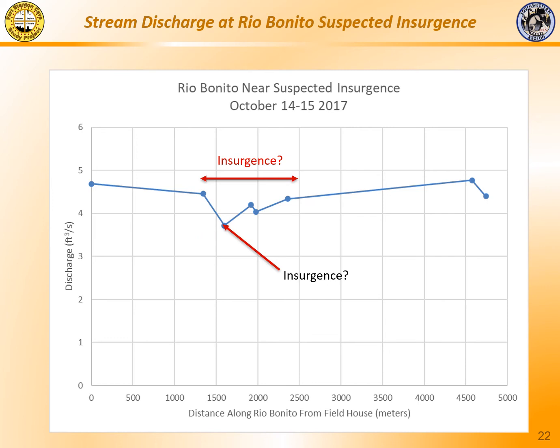So what's happening here? Well, each of these measurements has some error associated with it. If we make a really good stream flow measurement, we say it has a 5 to 10% error. If we're not in a nice straight channel with uniform flow, the measurement error can be much higher. And that may be what happened here: this measurement just had a larger error associated with it.